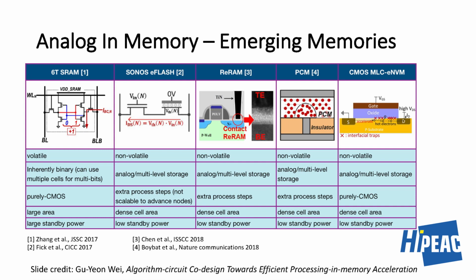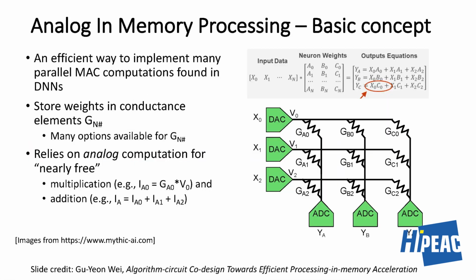But the cool fact about these new technologies is that they allow a very efficient, single cycle dot product among the memory bit cells. I was just showing it before, but imagine this is a memory array, an abstraction of a memory array where each bit cell is a resistor, which is storing some value. The value we are used to is 0 or 1 in SRAMs and DRAMs, right? Here it's no longer a 0 or 1, it's a resistance value. That's how you're storing it.